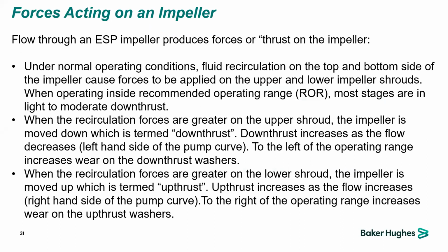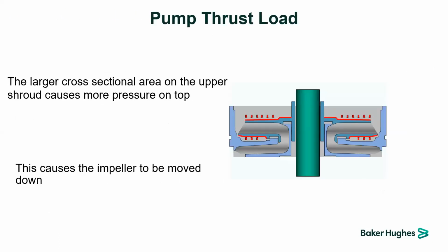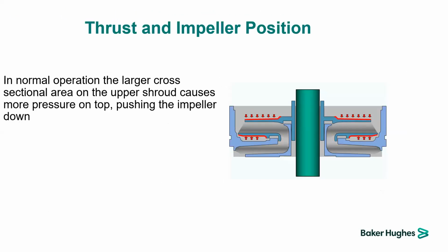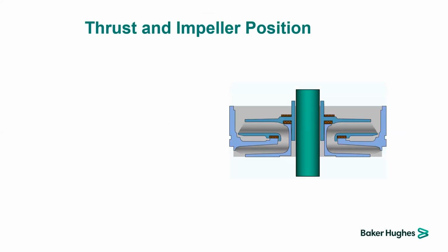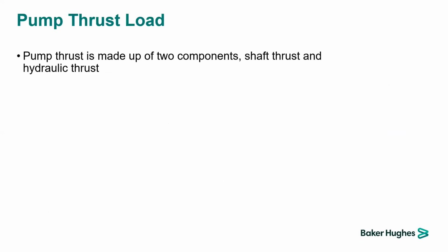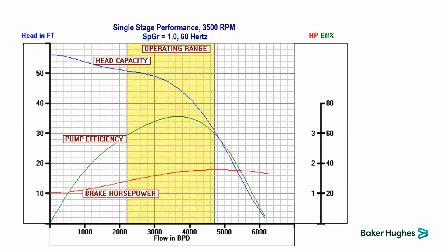Between the impeller and diffuser, there is some force acting on the impeller. That force is called thrust. In order to mitigate that thrust, we should be aware of something called the ESP performance curve. Let us go to that slide first and then come back again. Yes. For each ESP pump, there is an ESP pump performance curve. That performance curve indicates where we can operate the ESP.